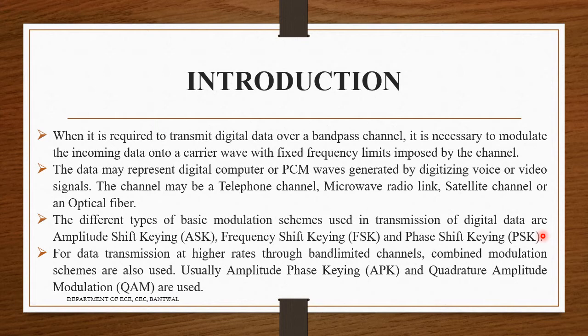We are going to study these three, but in this syllabus we deal only with PSK, FSK, and QPSK, and we have some basics of offset QPSK, M-ary PSK, M-ary QAM, and in the non-coherent type we deal with DPSK and also FSK. We'll go one by one.